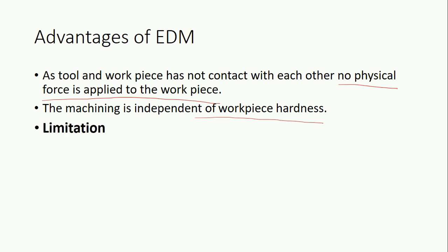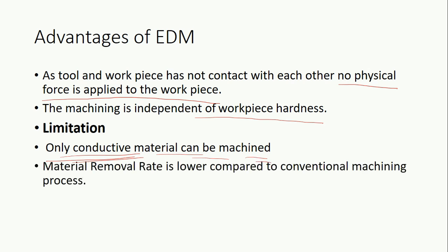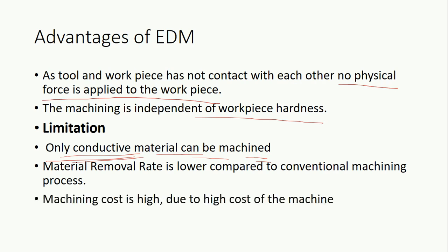But it has certain limitations. Remember that only conductive material can be machined. The material removal rate is very low compared to conventional machining processes like milling, turning, etc. And the machine cost is high, which creates a high machining cost.